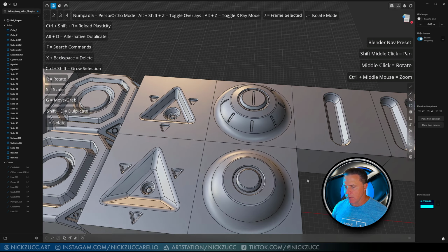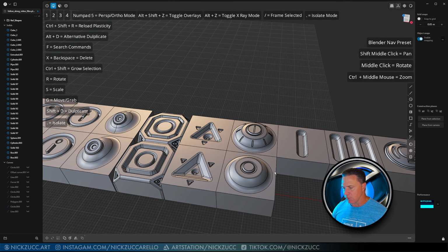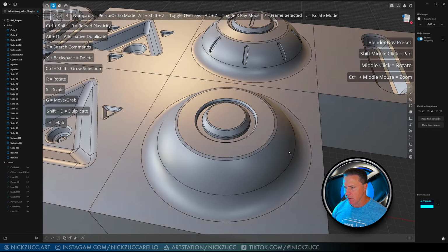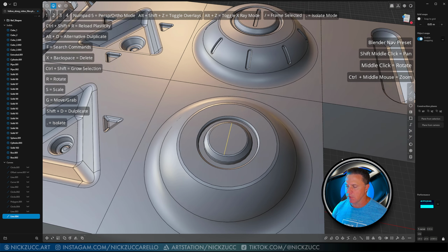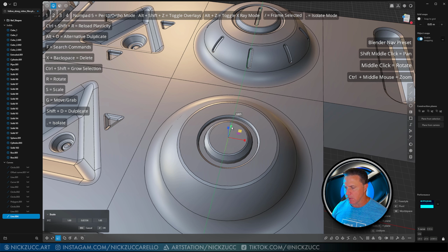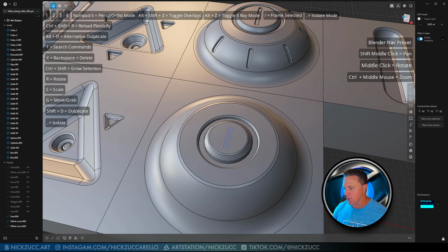Okay, so we've already looked at back here how to do some of these shapes like this over here, but let's just go ahead and do this together again. We'll select this line tool. I'm going to go from here to here, and I've got that snapping turned on. Right click to confirm, and if I tap S, I can scale this in this way like that. We select the curve, tap 2, tap O for offset, and let's see, yeah, we go here, just hit tab and we can choose the width of this. So let's go here right like that.